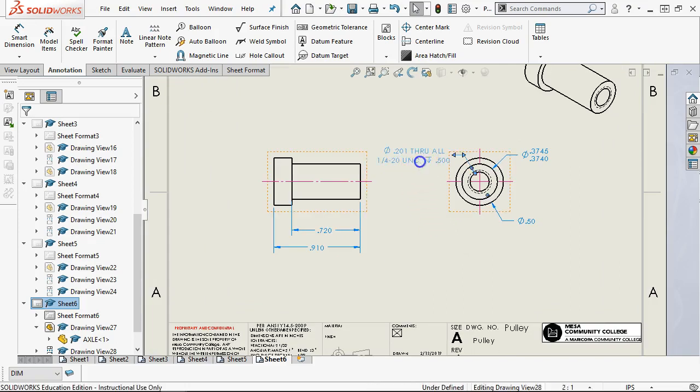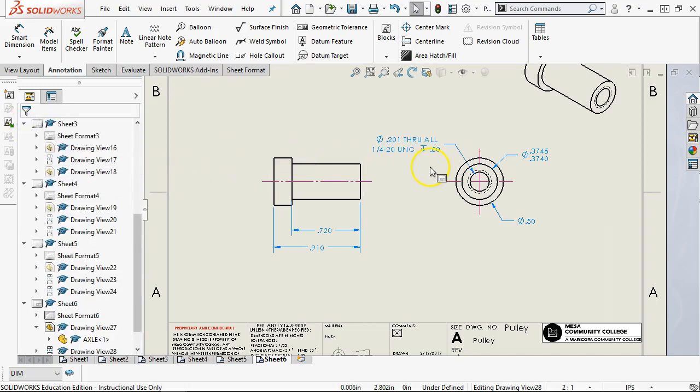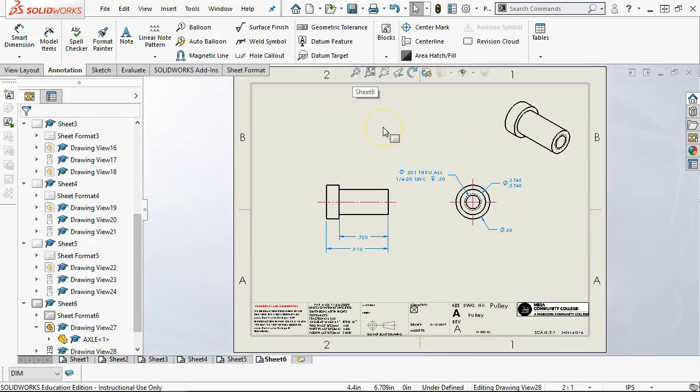So one of the things, the 1/2 inch plus or minus 5 thousandths: we'll go to the thread depth, and this is going to be a 2 decimal place. Even though we're not going to inspect to 2 decimal places, it takes the onus off the machinist of having to hold this to plus or minus 5. Don't need to. All right, so that gives us our drawing package.